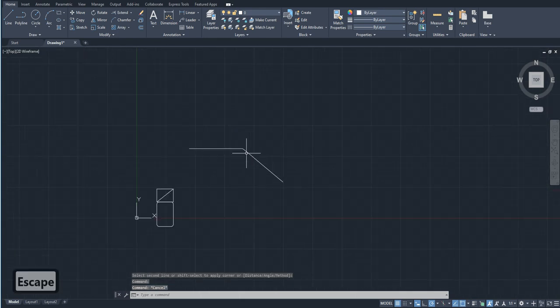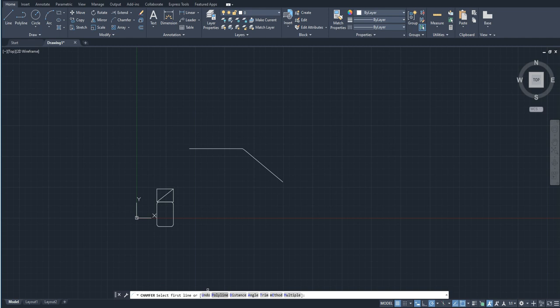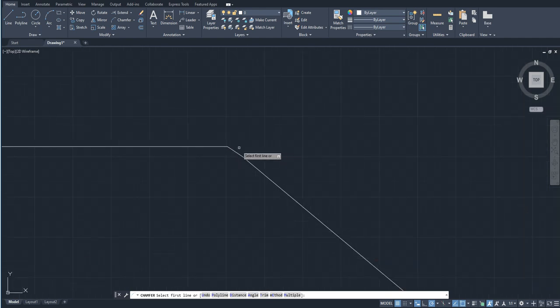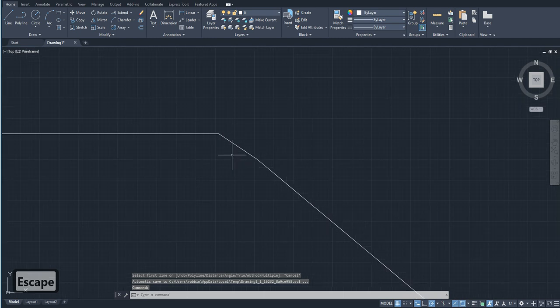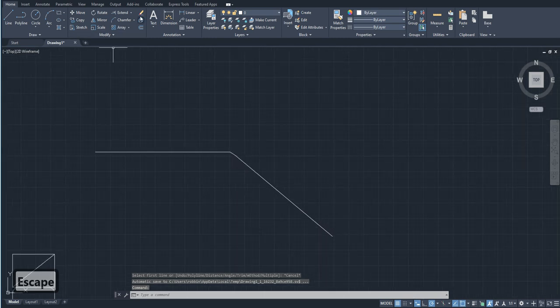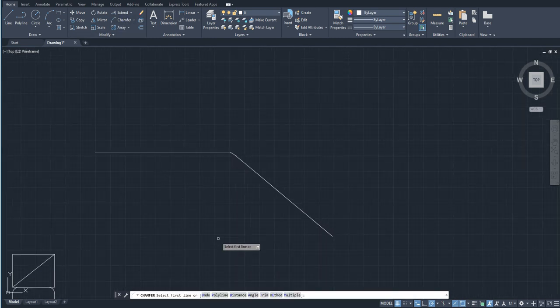If I just enter the chamfer command again, you can see it has similar options to the fillet command. It works in a similar way. I hope you practice on your own and understand how these commands work, except that what you have over here is the angle. Here I specified the distance initially. I can also specify the chamfer using the angle. If I just press A, enter,